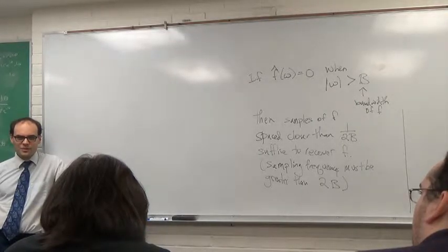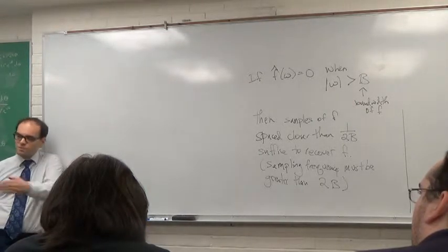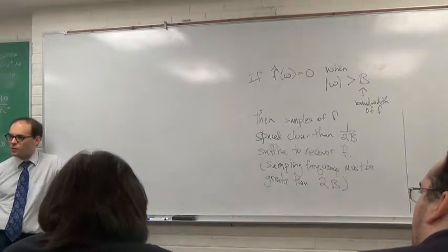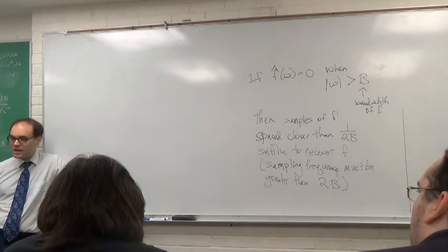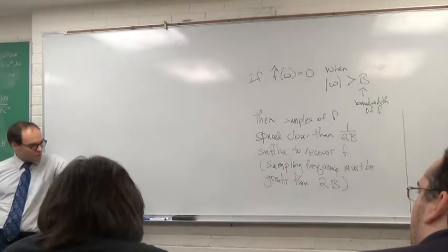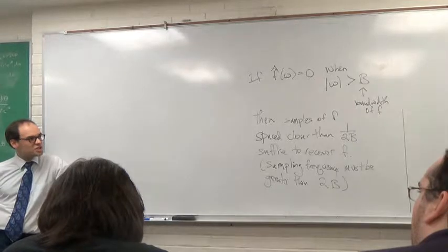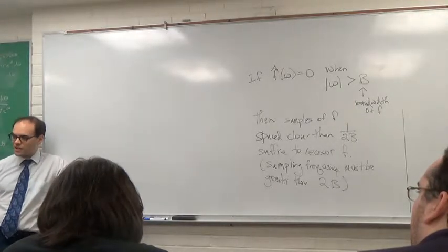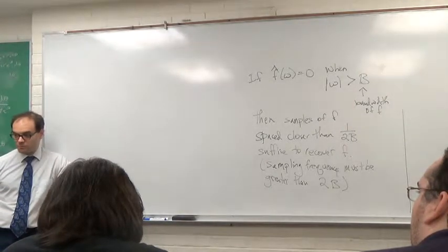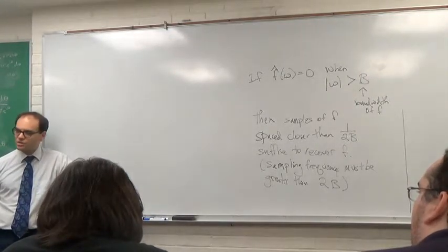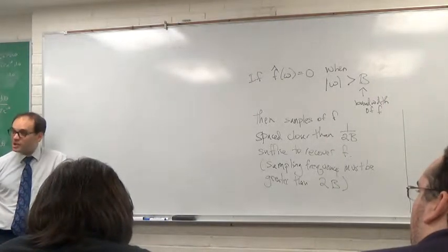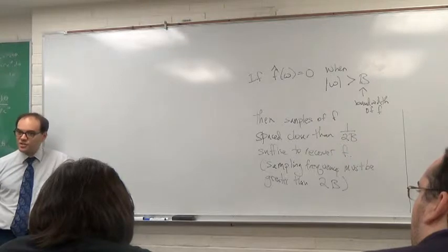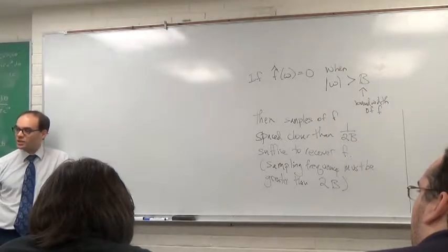What do we use thus far? The various people have used different ones. What sampling rates have you used thus far? You were synthesizing 8,000. So what's the largest bandwidth function you can hear with an 8,000 hertz sampling rate? Half of that, right? 4,000. So you can hear up to 4,000. Is that anywhere near the top of our range? No. So you can hear defects in the sound. Turns out 8,000 hertz is what the telephone system at one point used.